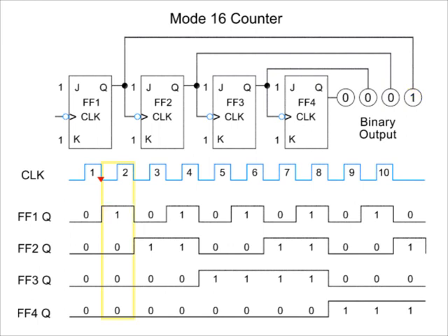When clock pulse 2 arrives at flip-flop 1, it returns output Q1 back to 0, which causes flip-flop 2 to toggle to 1. The output at Q2 is 1, and the count on the display now reads 0010. The counting continues, with each flip-flop output triggering the next flip-flop on its negative going pulse.